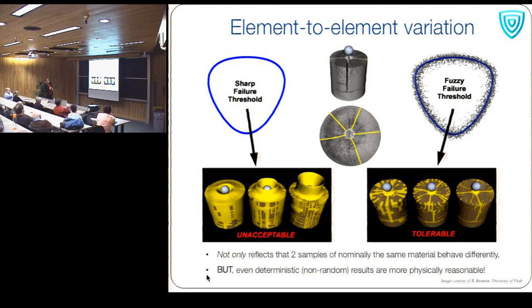And this is the experiment here, so you can see this sort of cylindrical sample being impacted by a sphere. From above, this is what the crack pattern looks like from the experiment. Over here, this just kind of seems to suggest that maybe the whole thing pulverizes or something. The yellow indicates damage. But over here, you can see that as you get to a fine enough mesh, you capture some of that radial cracking. So we're getting qualitatively better results.